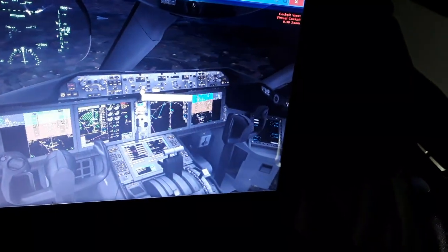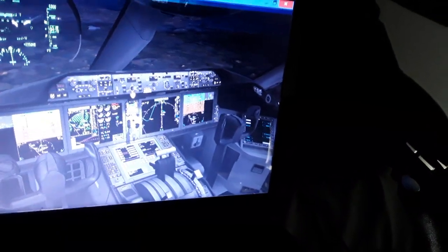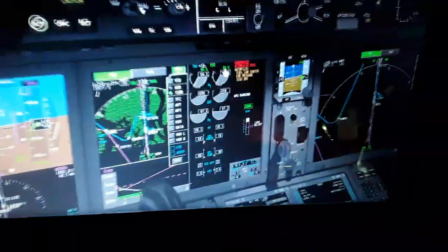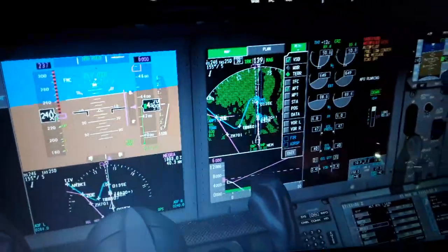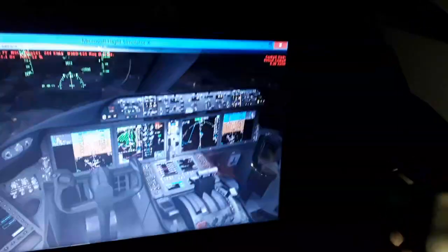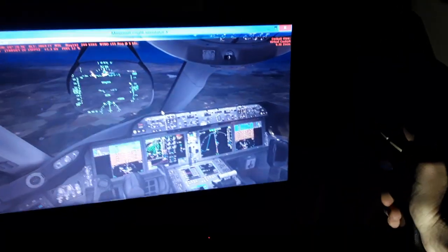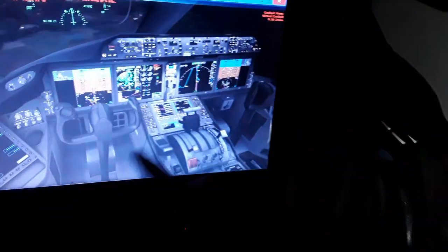The airspeed need to decrease a little bit. So as you can see, we are in the LSZH localizer over here, very close, aligned. You can see the indications. So we need only add some flaps. We have more or less 1 minute left for this flight to end, so we need to reach the point a bit faster.